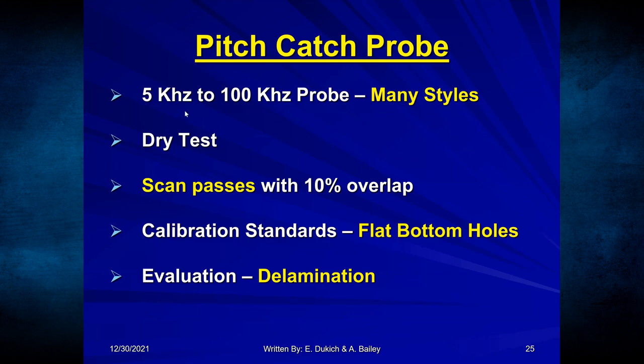For a dry test, we can use many different styles of probes. And I'm going to show you a couple of little videos here. The frequency that we're using, see, as an NDT inspector, I have to choose the appropriate frequency that can penetrate through all those layers and find the right flaw. And if I'm using a dry test, I have to be conscientious of the scanning technique. I make sure I have overlap. Well, really, we do that for wet and dry, but I have to be careful I don't scan too fast.